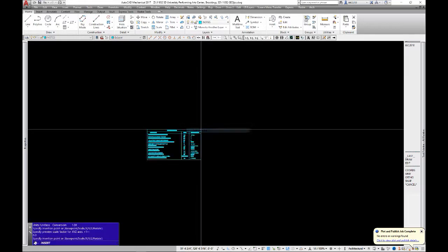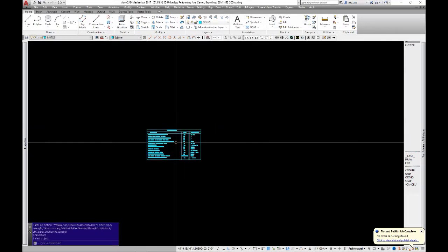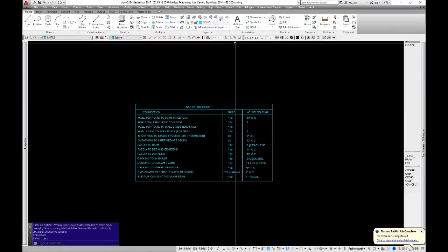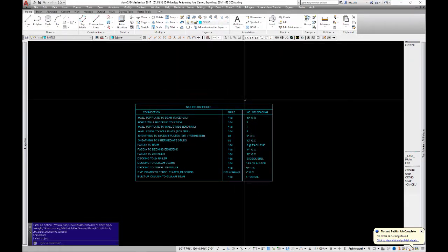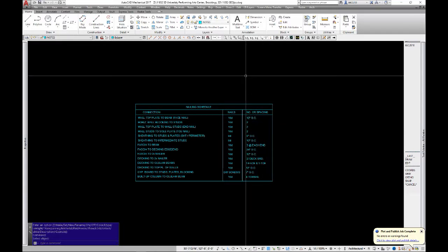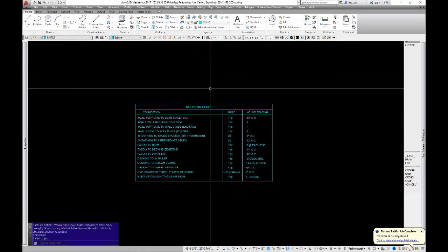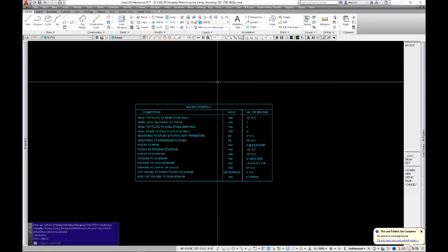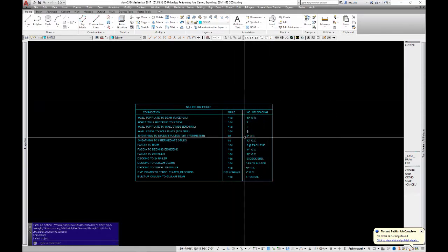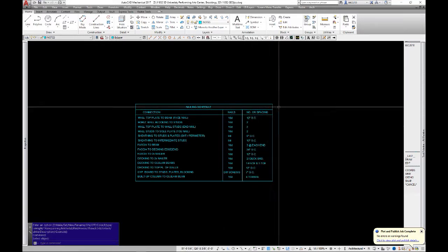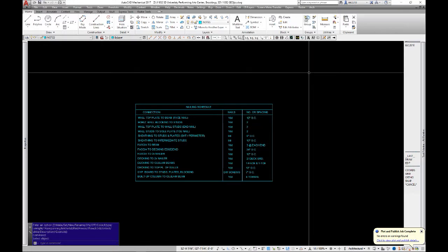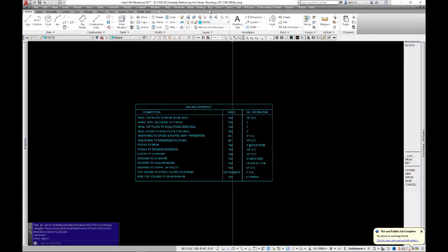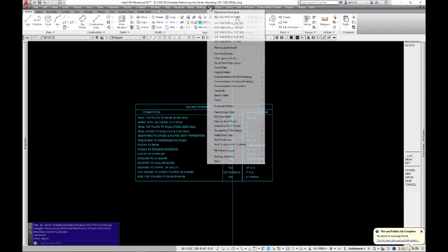Nail schedule. There's times when we'll need to put this on. Again, check with the engineer. Usually on jobs where it's required, they will have a copy of this in their calculation packet, and many times this stuff will get changed, so be sure that it is correct for the project you're working on.